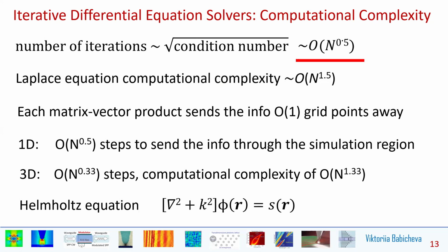So here the key term is a closed cavity. We can mitigate this problem of the non-convergent solution in the resonance, and for that we need to let the energy radiate to infinity. Computationally, we realize that by adding an absorbing boundary condition to absorb the energy at the edge of the simulation region. As a result, the system will not have a zero eigenvalue, and we can avoid the computational problem of ill-convergence. So let me repeat what I've just said, but slightly differently.